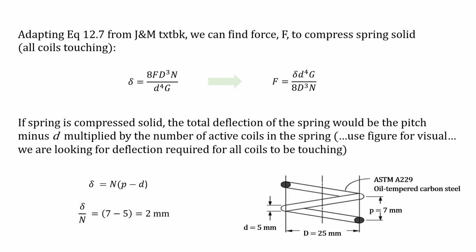And then because we don't know the number of coils in the configuration, we can divide our deflection by the number of coils, and then we can solve for that term. So we have our 2 millimeters here, and then you'll see that we can just plug that into the force equation from equation 12.7.